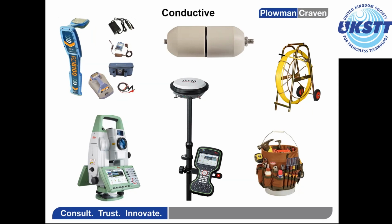When tracing cables via Cat and Genny or EML, the measurements are taken from the center core of that cable in the best case. When locating or detecting metallic pipes, as they're hollow, they can emit a signal from any point around their circumference.